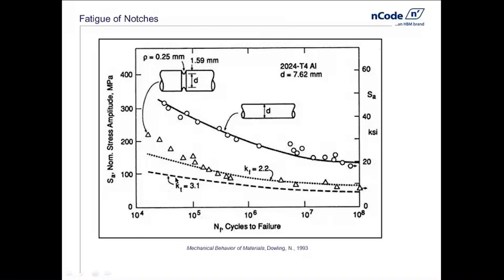However, if I were to take that part, create that part with the notch, and do a fatigue test on it, I may not get that poor performance. In fact, in this case here, you'll see the second curve up, it actually gives you a much higher fatigue performance. A performance that here it's saying is a notch factor of 2.2.